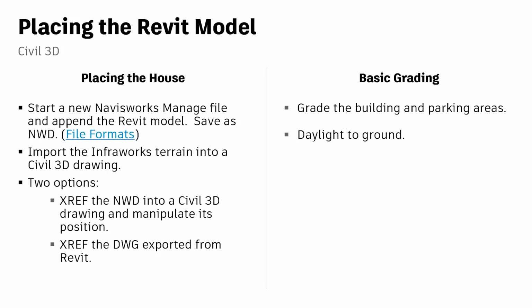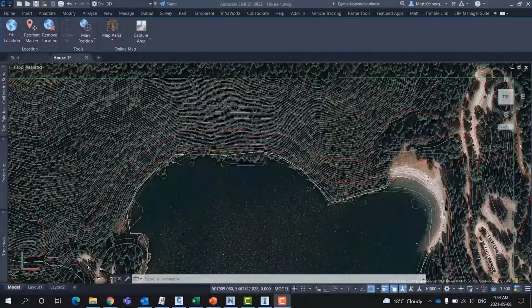What's the advantage? Well, using Autodesk's shared reference point, we can define 2 points in the AutoCAD model and the Revit model and tell the software these 2 points are synchronous. When the Revit designer exports to a DWG, as long as those shared coordinates have been defined properly, you can XREF it 0, 0 and everything will line up properly. I'll show you the Navisworks option first.